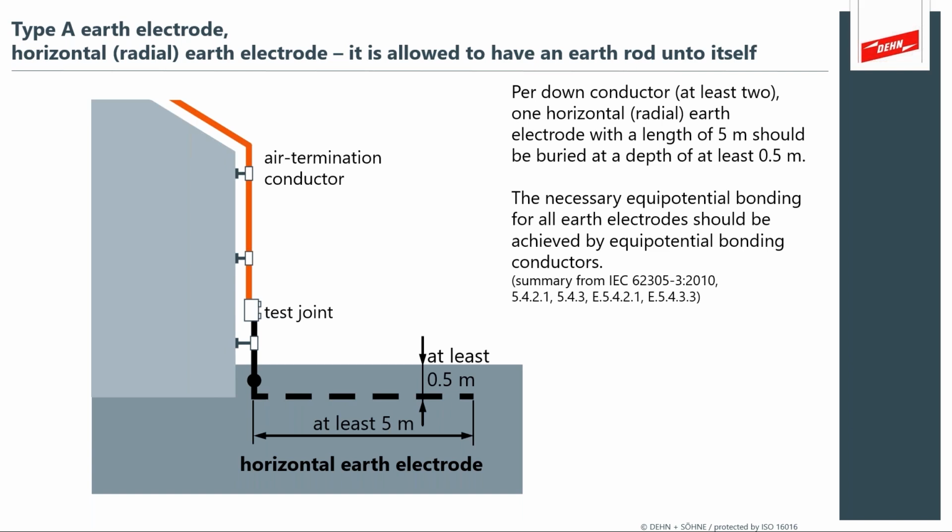Here in the USA, the Article 250 for your AC power earth electrode is 25 ohms. So that can be achieved by going back to that calculator, running that earth electrode the distance required to get 25 ohms. We have customers that mandate that they want a 1 ohm connectivity to the soil. You'll see things from other customers where they'll talk about 5 ohms.